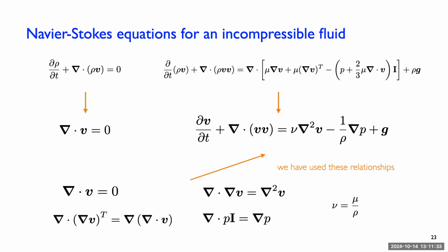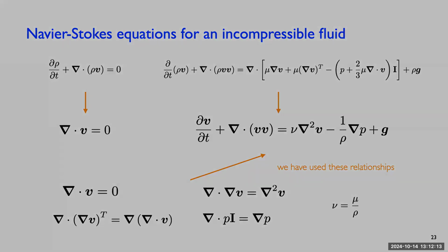And then typically in incompressible fluid solvers, they will divide across by the density. So they'll just divide the whole equation across by density, so the density only appears in the pressure term. And some fluid solvers will just bring this pressure over density and define that as the pressure. So they call that kinematic pressure. Kinematic pressure is just pressure divided by density. So when we go to use OpenFOAM, it's incompressible fluid solvers. They're independent of, let's say, density, and just solve directly for pressure over density, called kinematic pressure. And then they will also often introduce a kinematic viscosity. By kinematic, I just mean divided by density. So these will be the set of equations that we'll actually solve.